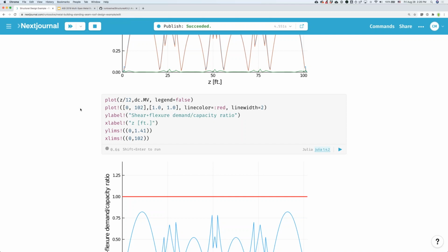But the limit state predicted is totally different. So something is amiss. Well, what you saw was with sufficient spring stiffness, then it's failing by distortional buckling. But for uplift, it was failing over the support. Yeah, for uplift, it was failing over the support. Whereas the code equation, well, it's just a multiplier. Like we'd have to go back and look at the test to see how things failed there.